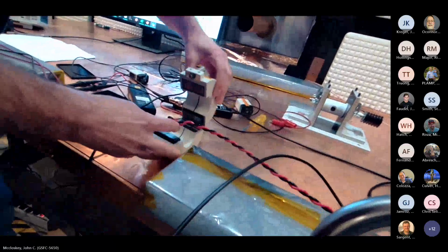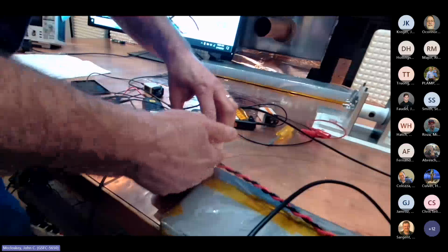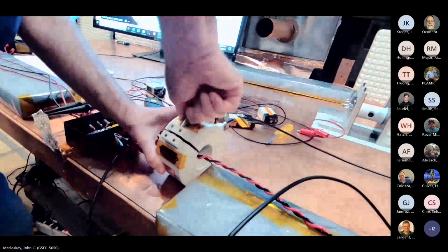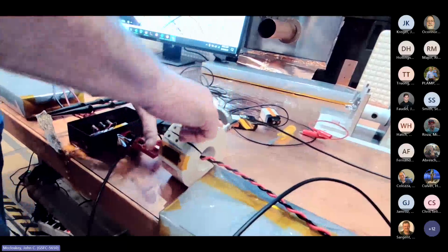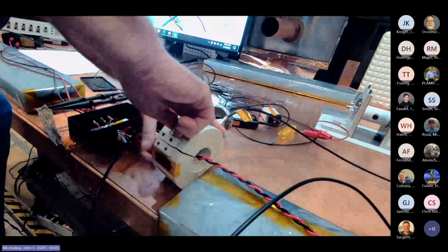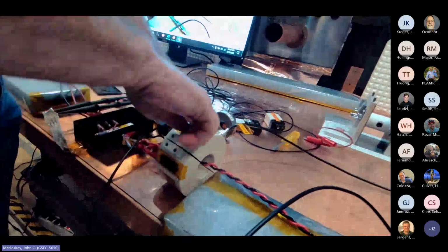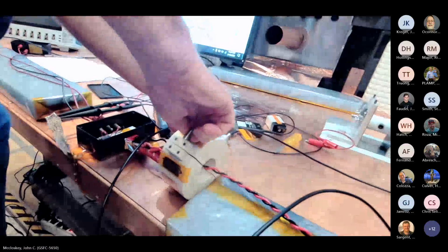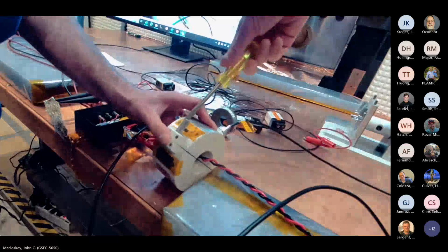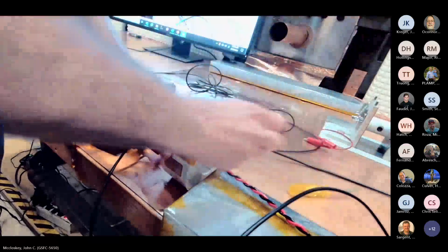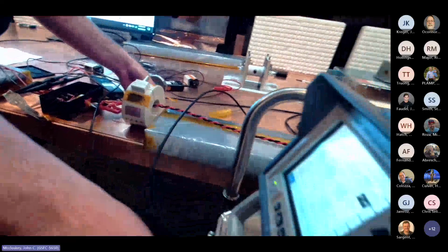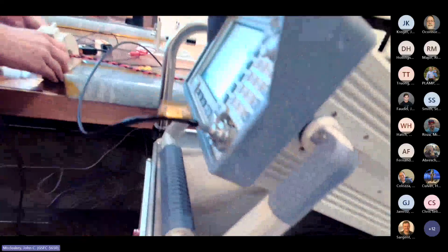So I'm going to connect the probe around both wires. So it's the composite bundle for common mode. For power lead, it's just positive and negative leads. If it's a shielded cable, you just clamp it around the entire cable. And you see it just clamps on. You don't have to disconnect anything.